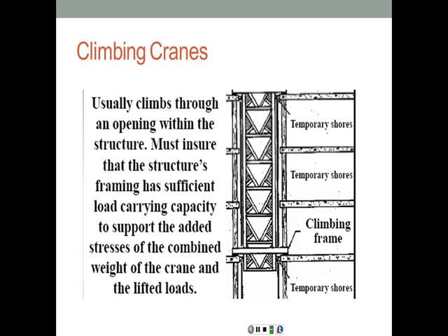For the climbing cranes, the crane can basically self-erect itself, usually climbs through an opening within the structure, and you must ensure that the structure's framing has sufficient load carrying capacity to support the added stresses of the combined weight of the crane and the lifted loads. So this is within a core of the building itself or something like that.